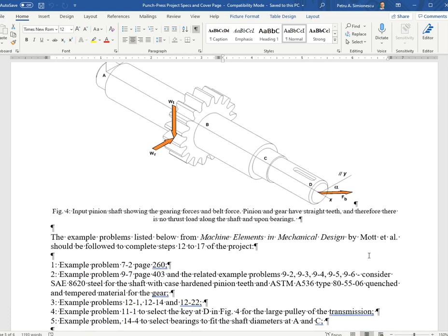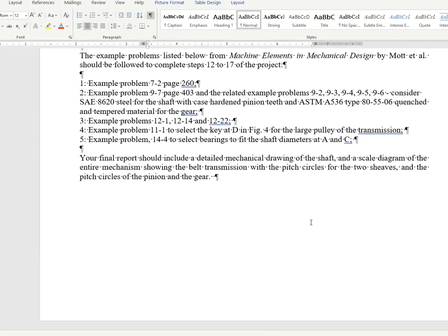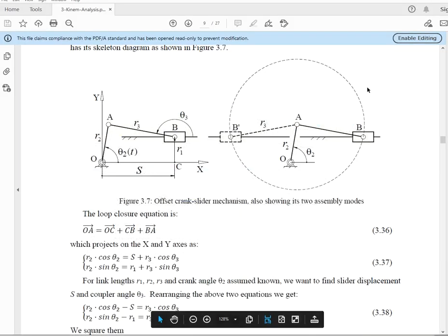Okay, so if you go to the notes, you have an eccentric slider crank or crank slider mechanism. Crank is the input, slider is the output. Slider crank would be like in a piston engine, where the piston is the input.